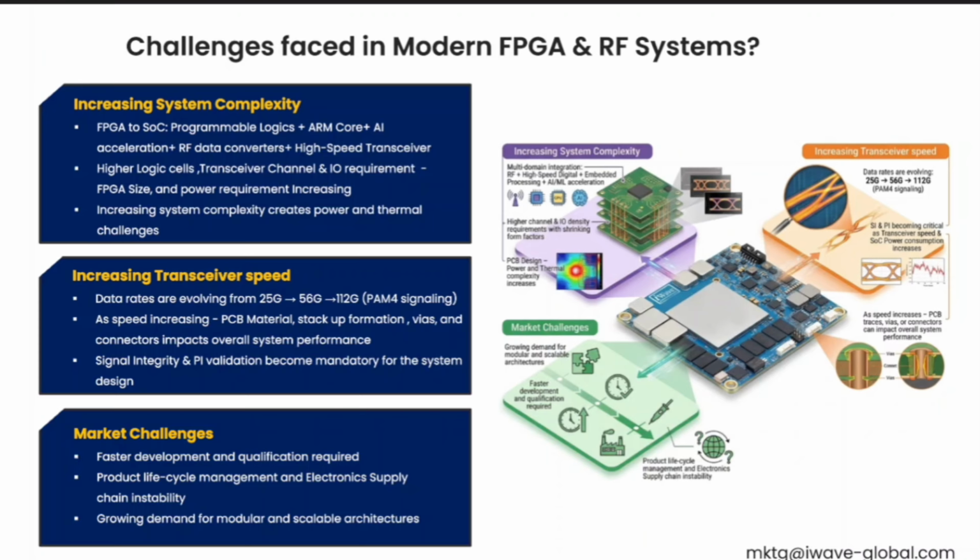Here the FPGA is placed on a small PCB and all FPGA-related power, clock, and memory circuits are taken care of, so that they can just buy an off-the-shelf FPGA module, plug it into their carrier card, and directly start working.